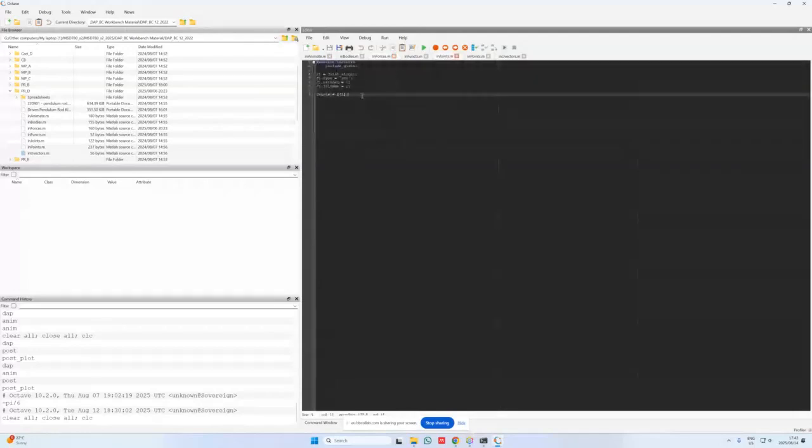If you look at in joints, the only joint that we specified in this case was the revolute joint, and this is where the pendulum rod is swinging or is hinging on the ground. So we don't have any relative rotation driver that we specify on this system. So technically we're working with a strictly forward dynamic analysis in this case.